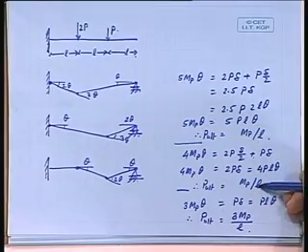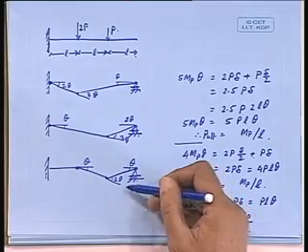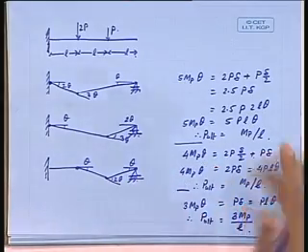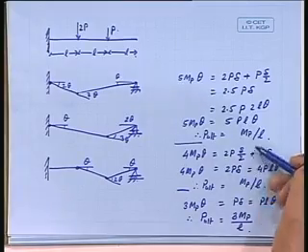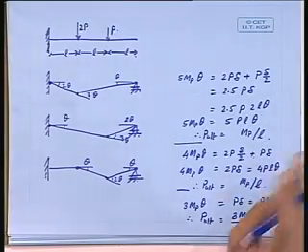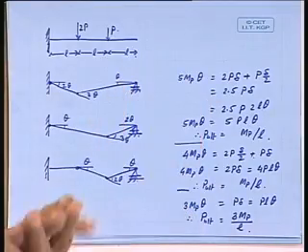So now you see, this has got MP by L, this has got MP by L, and this mechanism has got 3 MP by L. So the last mechanism is out of question. It can be either this mechanism or this mechanism, because both have got the same ultimate load, and it's only the imperfection in the structure or slight imbalance in the load. You say it is 2P or this is P, or there is a small difference in the time of loading, the quantity. It can take either of these mechanisms for failure.